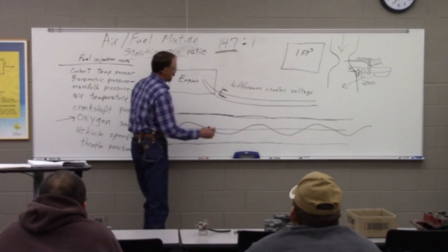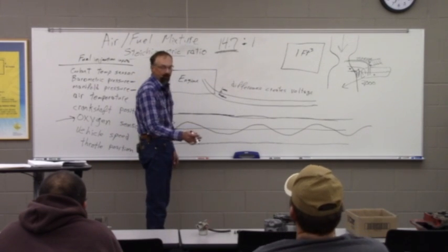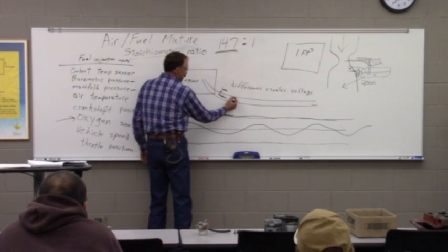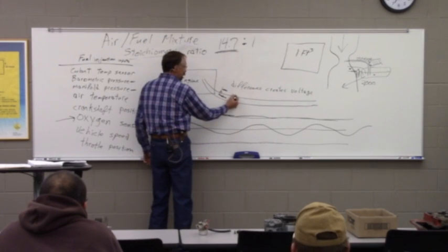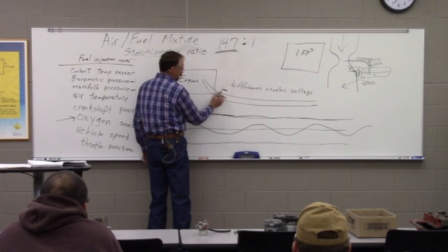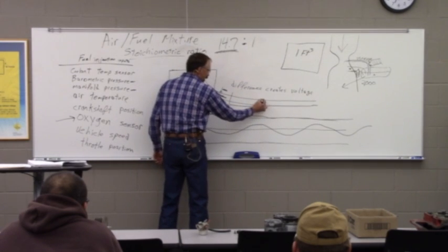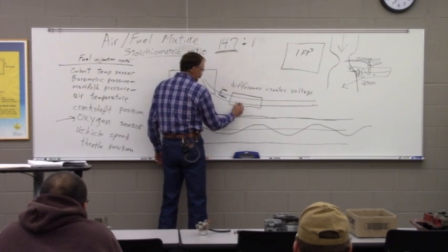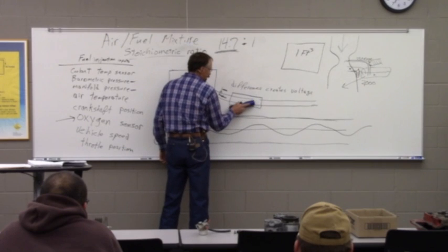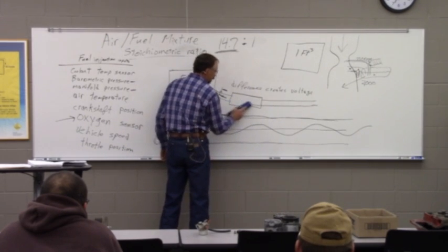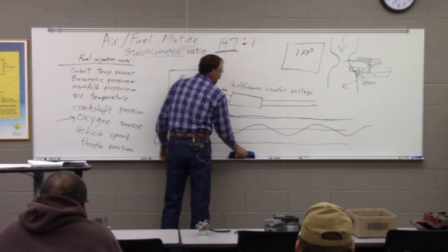Now, one more thing of interest while we're on the subject of oxygen sensors. What's commonly been done for the last, I don't know, 15 years at least, is there'll be an oxygen sensor right up there near the engine. Then we're going to have this catalytic converter, which is a device engineered to take some of our incomplete combustion.